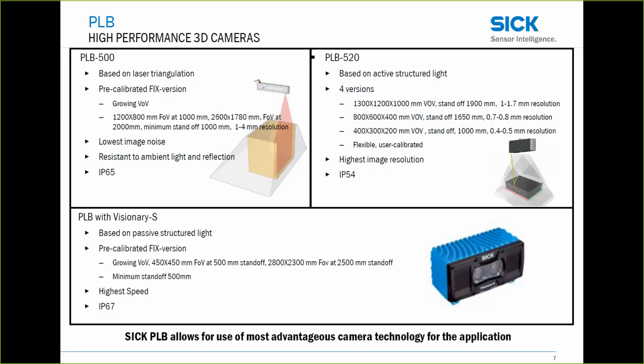The main thing with this one, though, is you get low image noise. We're not going to see a whole lot of noise in the image, a whole lot of artifacts or anything like that. And we're very resistant to ambient light because we're just looking at that laser as it comes across. We're not working with a projector or anything. So it's very good for varying light conditions. The other nice feature of it is IP65. So you foundries out there, this guy works well. It doesn't get dust in it or anything like that.